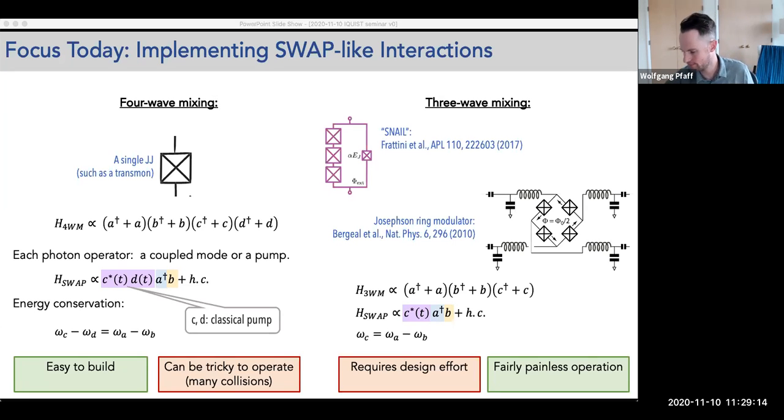Well, I wouldn't say they're out of the question necessarily, but this operates purely in a very strictly dispersive limit where we don't have to consider anything other than really the modes of the superconducting circuit themselves. So I don't have to even think about, say, properties of the superconductor, besides, of course, the behavior of the Josephson junction. So I wouldn't say it's out of the question. I would say from this point of view, I don't have a need of thinking about something like that, because to me that seems to add just a lot more complexity to the story.